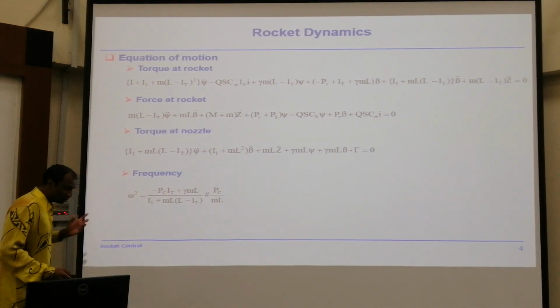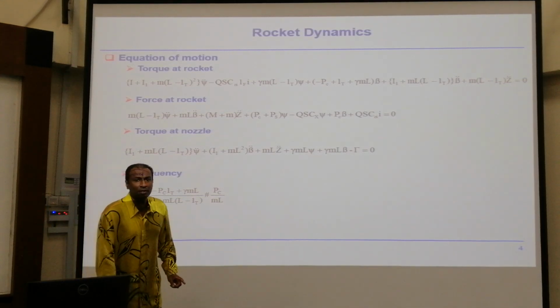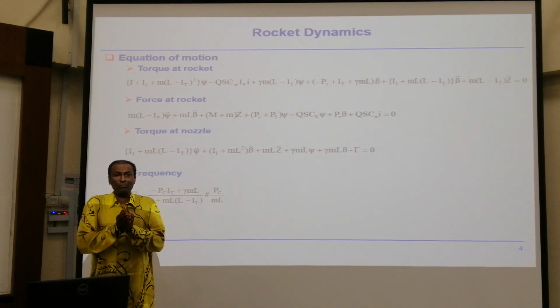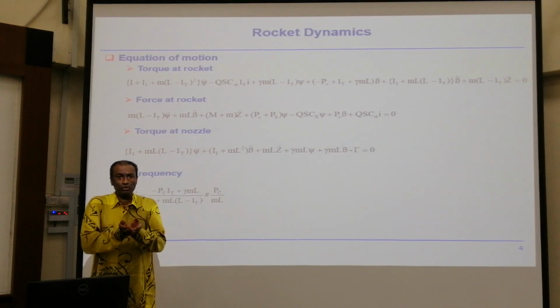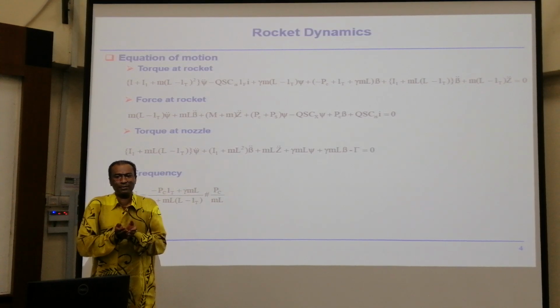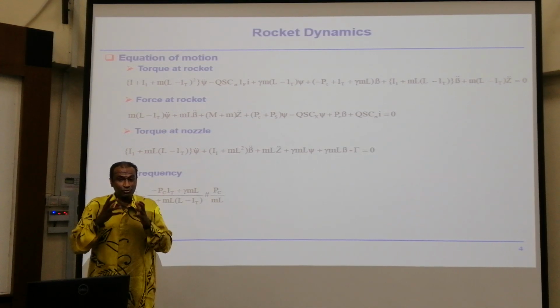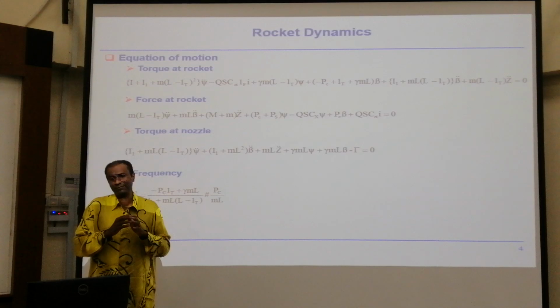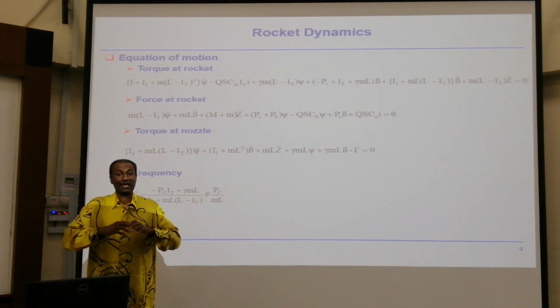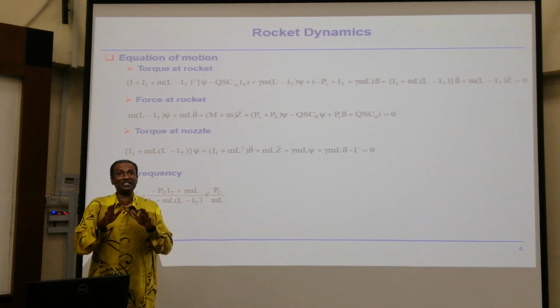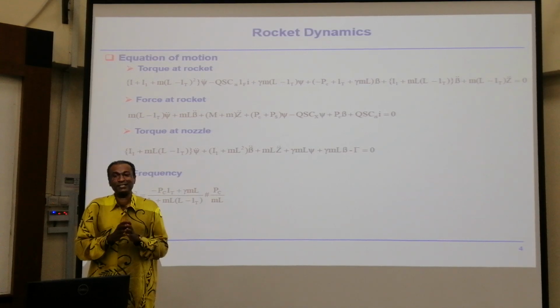Now, why is it so important to know this frequency? Now, you are going to put a payload. Assume this frequency is so high, it can even break up your payload. So it's very, very important to know the actual frequency in terms of dynamics, so that you know that you are in a safe regime, and your payload or your satellite will be safe before it is actually injected into